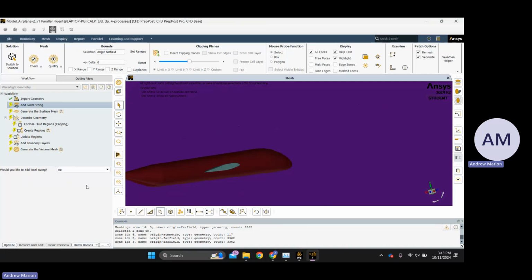You can just look up how to do it, but essentially you take the solid of your aircraft and the solid of your volume and subtract the aircraft from the volume. It should cut a hole in the volume, the exact shape of the aircraft, and then delete the aircraft.